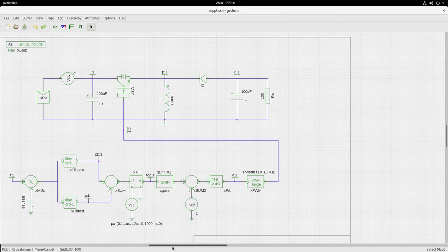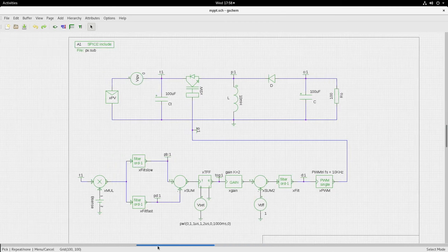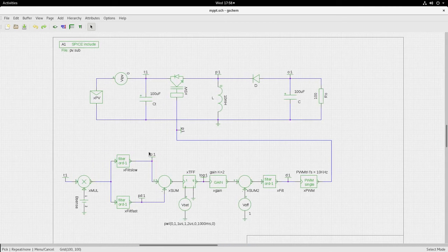So now we will go to performing this simulation. So what is it? This is existing, which we had done before up to this point. We are now going to give this in a closed loop way, sensing the voltage and the current. And we expect that whatever may be or not, this will always go and adjust the value of the duty cycle in such a way that maximum power is drawn from the PV source. Now that is what we want to see.